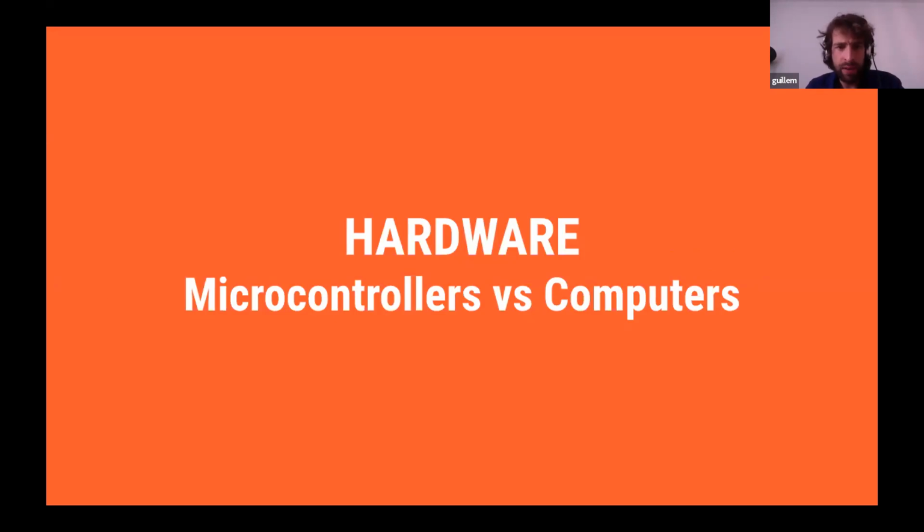But nowadays, with this idea of system on a chip, it's hard for me, in fact, to tell you if an ESP32 is a computer or a microcontroller, because you could actually connect a screen to an ESP32 and even install maybe a small operating system, like a reduced version of a Linux system. And at the same time, you could treat it as a microcontroller and not do so. So what I'm telling you is that it's good to distinguish a computer from a microcontroller, but actually the line is getting really, really blurry.